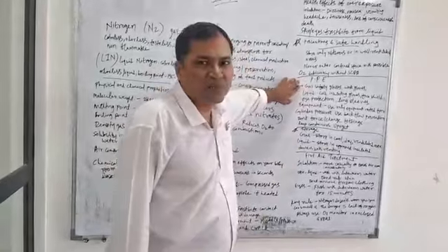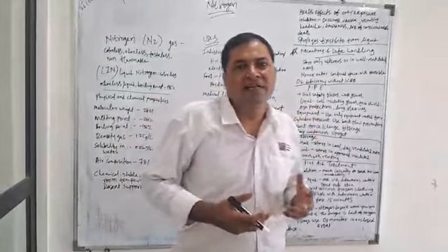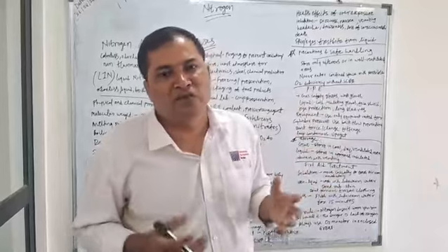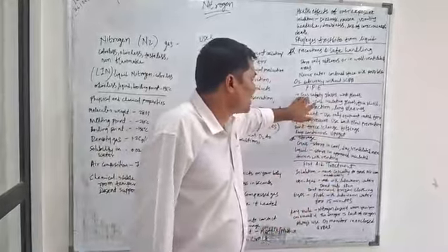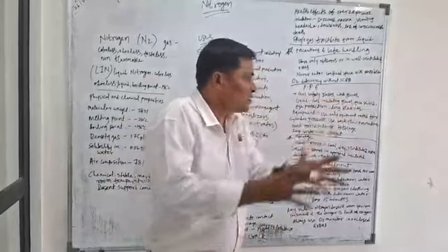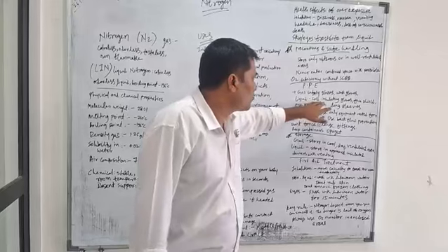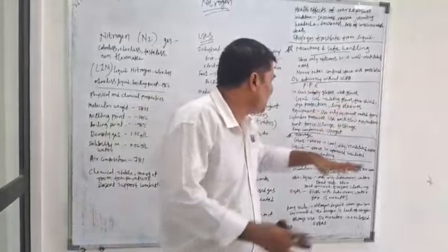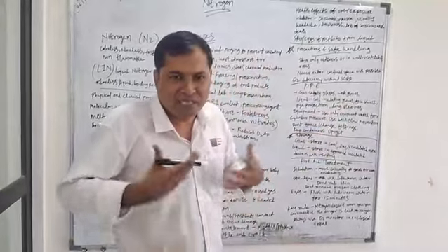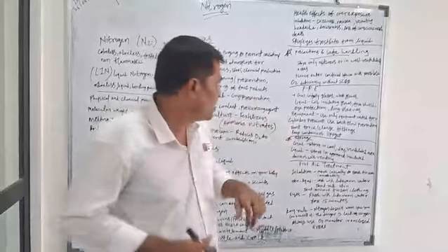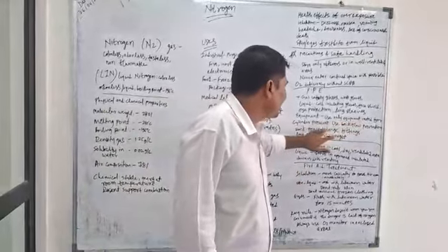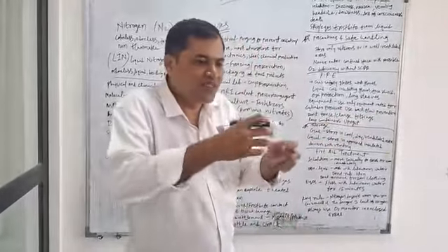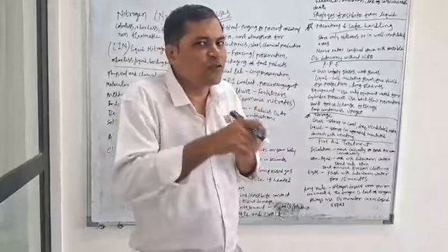For PPE, personal protective equipment, what is required to enter the nitrogen zone where nitrogen production is going on? For safety, gas safety glasses, proper gloves, cold insulating gloves for liquid, a proper face shield, eyeglasses, long sleeves, and a special apron. So you need to wear the special apron. For equipment, use only equipment rated for the cylinder pressure, use backflow prevention, and don't force any fittings. If there is any fitting or equipment you need to replace, don't force it.